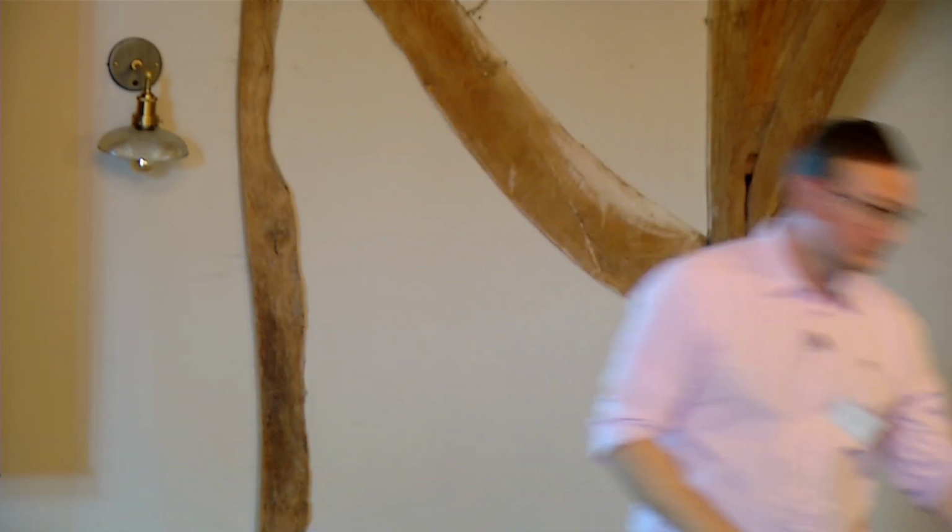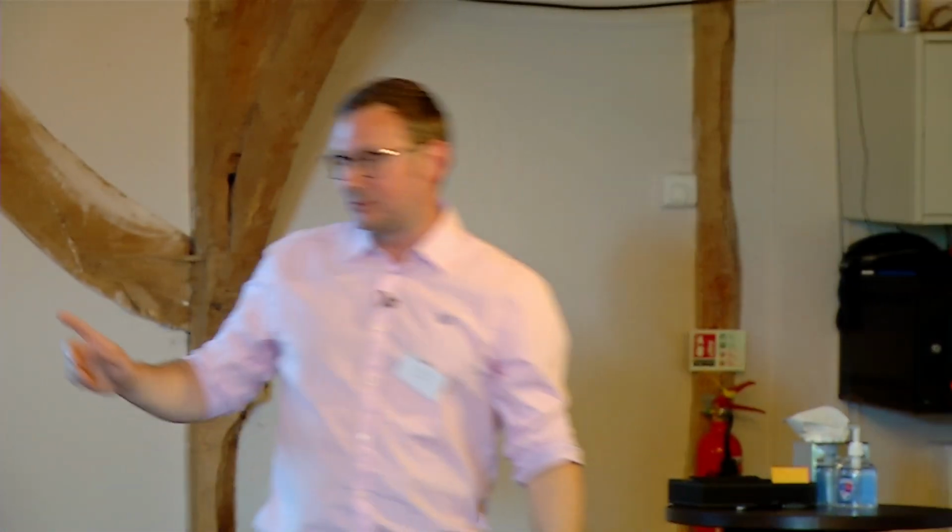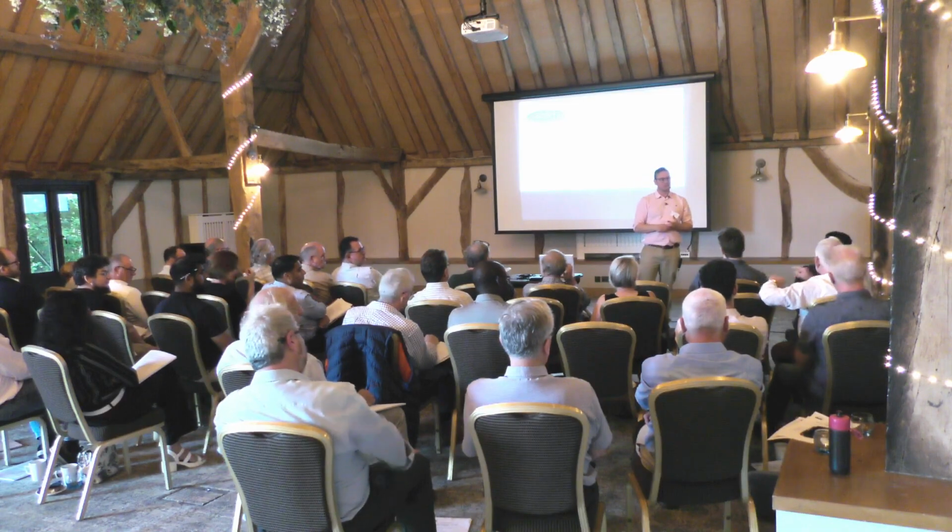So you speak to your client and they say, oh, in 6 months' time, we're going to open up the ground floor. Well, maybe then what you should think about is explaining to them that if you're doing these works, additional requirements would kick in. I think that's a given. It was more about what other advice could you give other than smoke detectors. I said you could put a sprinkler system or another sort of alarm system in. So ADB is clear that it says protected corridor or a sprinkler system in accordance with BS 9251. But I'll come to that next. Sorry. No, you're fine. Go on. This might be just beyond your field.